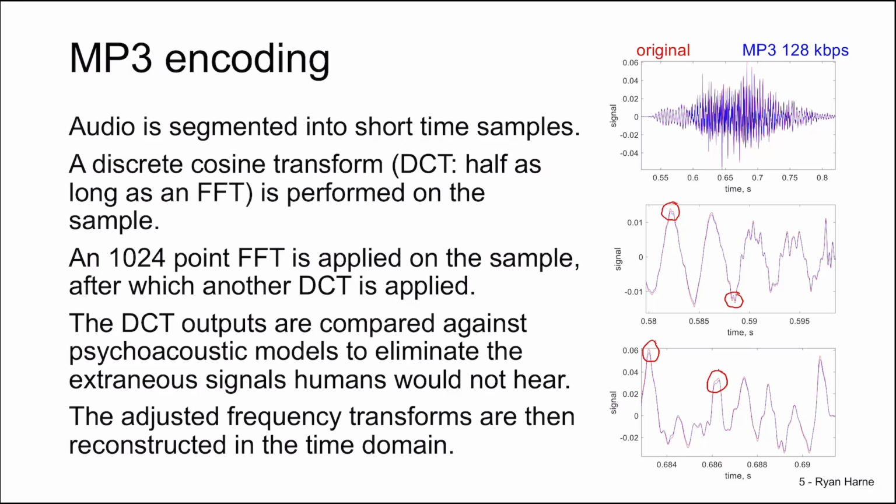This is indicative of the fact that fewer of the sinusoids or cosines are used in the reconstruction of the MP3 compared to the original signal. This is then justified through the audio recording sizes. The original audio recording in a WAV format had a size of 873 kilobits, whereas the 128 kilobits per second MP3 was only a 41 kilobit file size, a significant reduction despite not much reduction in the quality of the sound.